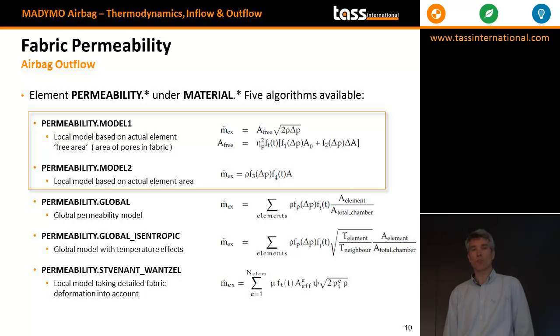That might look strange. The reason for that is, typically for uniform pressure, that you would like to control the outflow in time. For permeability that maybe doesn't make that much sense, but for holes it's maybe easier to understand. If you have a folded airbag, holes might not be directly active because they are closed, because there is no gas located there.